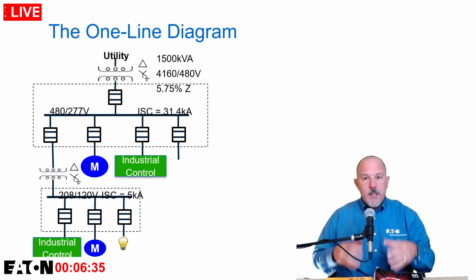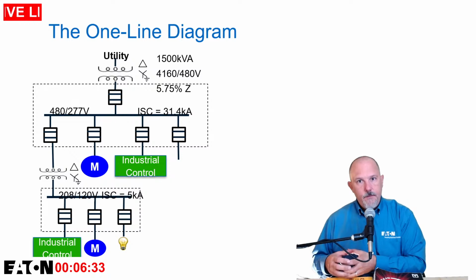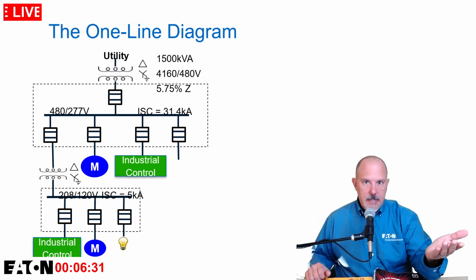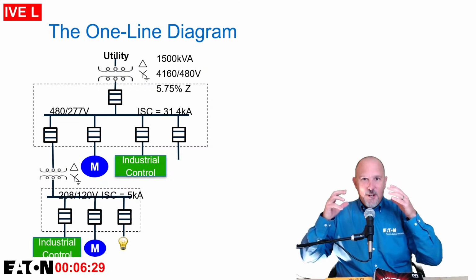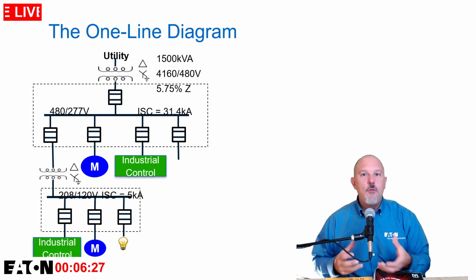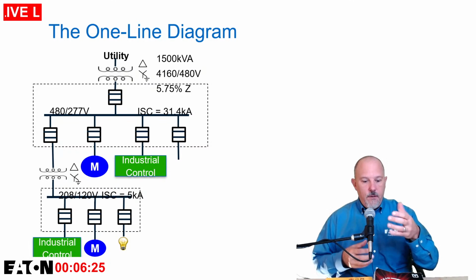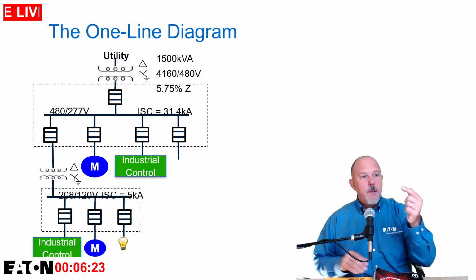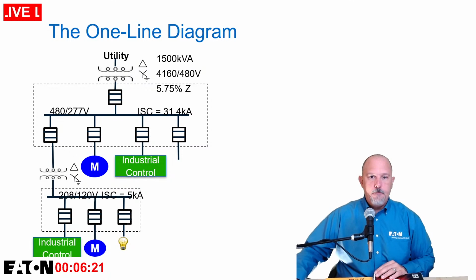So you'll want to make sure you date the one-line diagram. I mean, not to take it out to dinner or something like that. I want you to put the actual date that you drew that diagram and you verified the data was accurate. Put that on the diagram.